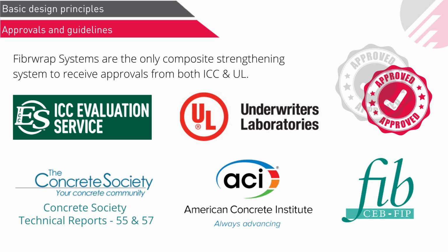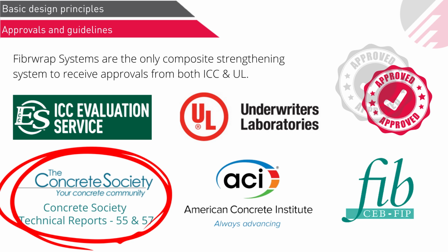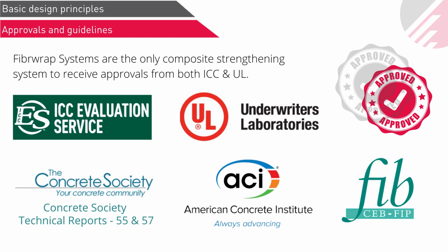Yeah, it doesn't need fire protection. That could be the case. In fact, in most strengthening schemes, you will find carbon fiber doesn't need fire protection because of the structural requirements. But in terms of building control requirements, if that is needed, then there are different types of fire protection systems that can be used. Now, in terms of design, if we are designing in the UK, then the document to follow is the Concrete Society document TR55. That's the design guideline to design FRP in the UK.